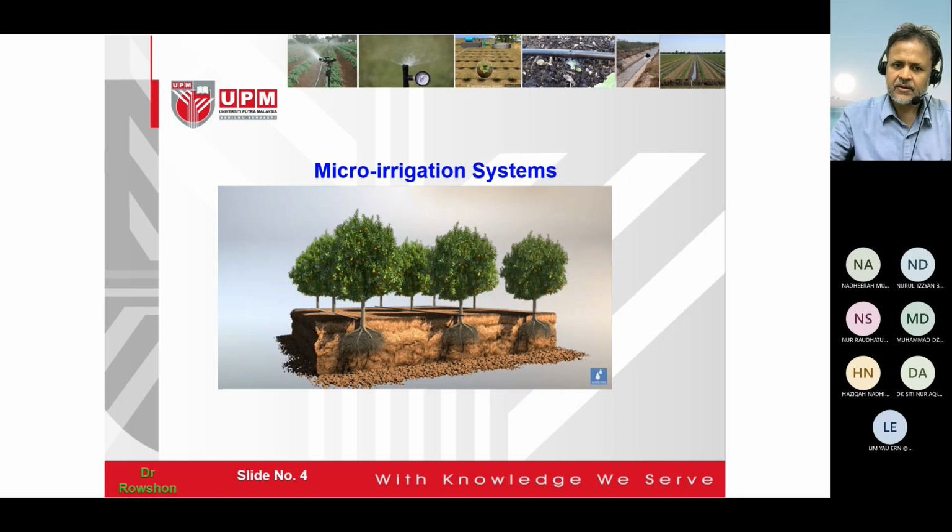So when the crop receives full water, it reaches field capacity, which is 32. Then we decided MAD is 20%, somewhere here. So when moisture content is 20%, we will decide to irrigate.